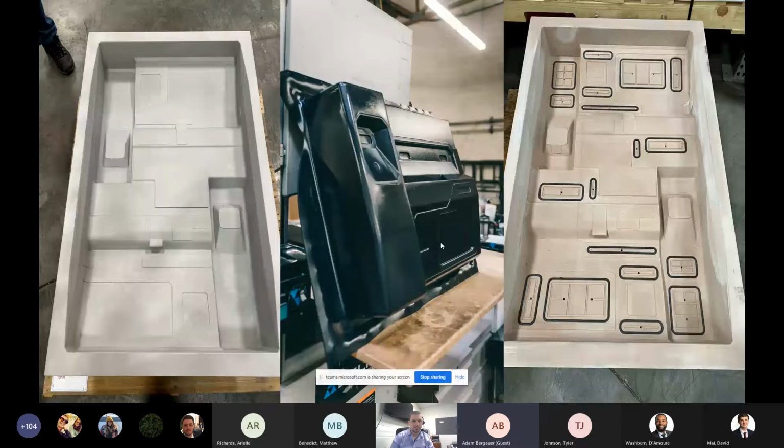This is an example here of female tooling on the left side of the screen. This is a fully cast aluminum tool that we then fully machine back. You can see there are some really tight radii in here, which our customer really wants. This is what we call a 2-cavity tool. So it's basically this right here, just flipped upside down. We do this on parts where we have to produce over 1,000 or so. Otherwise, we would just make a 1-cavity tool. You basically make the same parts twice as fast.